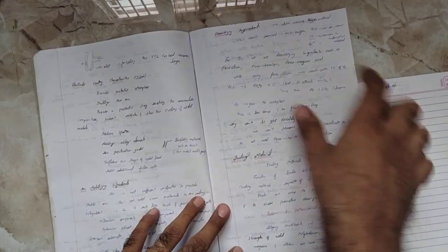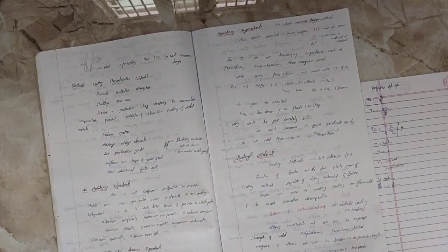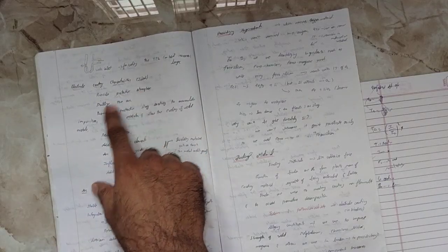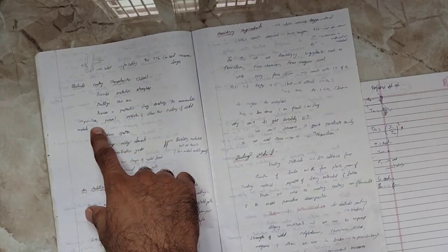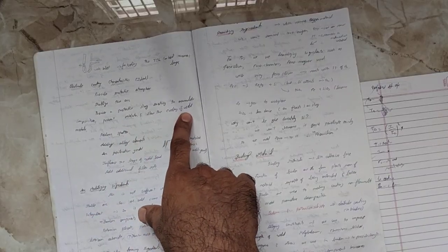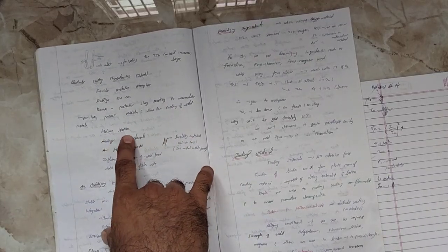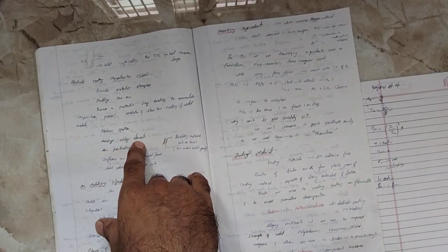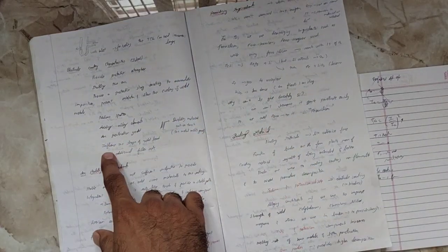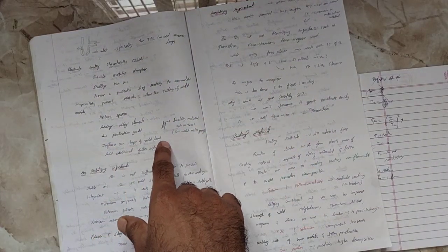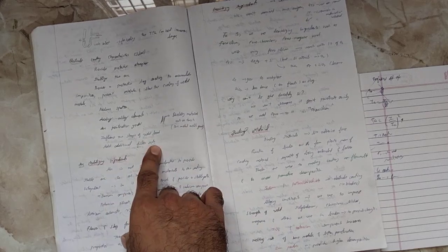So the next thing, you can see electrode coating characteristics. The electrode must be coated. You can see it provides a protective atmosphere, stabilizes the arc, and provides a protective slag coating to the accumulated impurities, which prevents oxidation and slows the cooling. It reduces spatter and adds alloying elements. Arc penetration is good, and it influences the shape of the weld bead and adds filler rate.